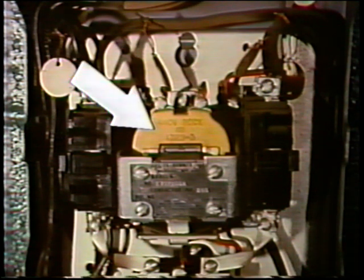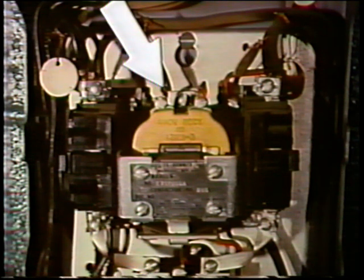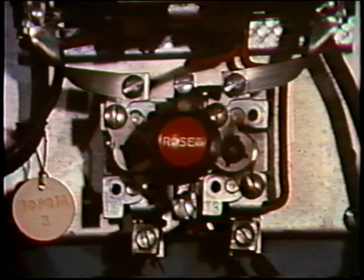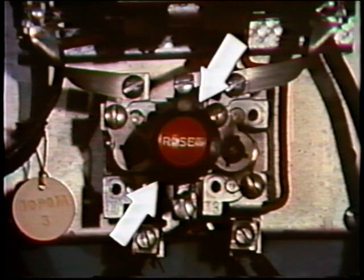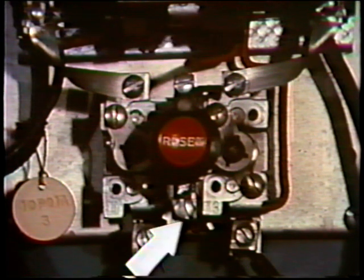Now let's locate these parts in the actual controller. The operating coil is located in the controller at approximately the same place it's shown on the wiring diagram. As shown in the wiring diagram, the magnetic contactor's contacts are positioned on each side of it. The auxiliary contacts are electrically connected to the operating coil by this wire and to the master switch by these wires. The overload contacts are located in the overload devices and are electrically connected to the operating coil by this wire and to L2 by this wire.